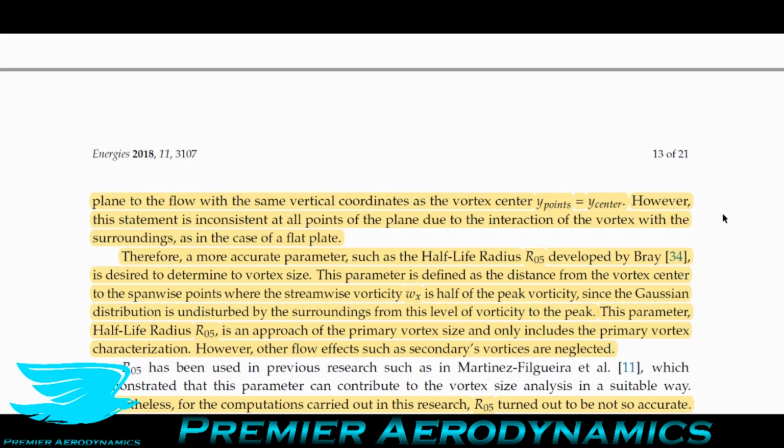So what this means is if you have a vortex next to the wall, let's say it's 1 meter away from the wall, you theoretically have another vortex, which is 1 meter away from the wall on the other side in the exact same alignment as the vortex you do have in reality. And this vortex on the other side will be affecting the vortex in reality as well through inducing the flows and the velocities and also potentially breaking down the vortex.